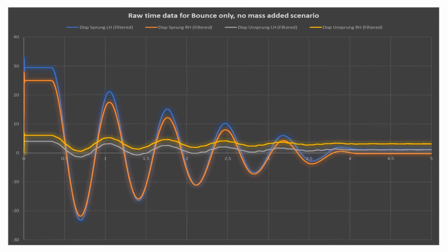So basically you can clearly see here that we've got offset, and the point is that we cannot simply AC couple to remove this offset, because the AC coupling is a kind of high pass filter, and so for these low frequency signals, such a filter would also attenuate the vibration frequencies of interest. And so we need to remove the non-zero offset by some calculations for both left-hand side and right-hand side displacement signals.